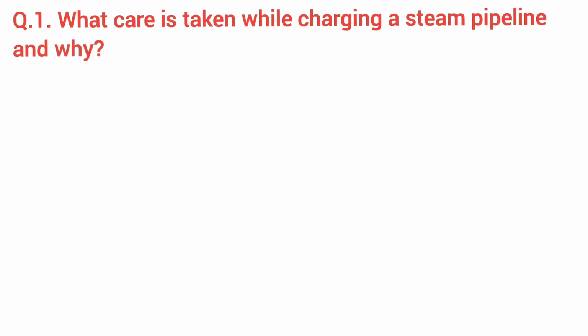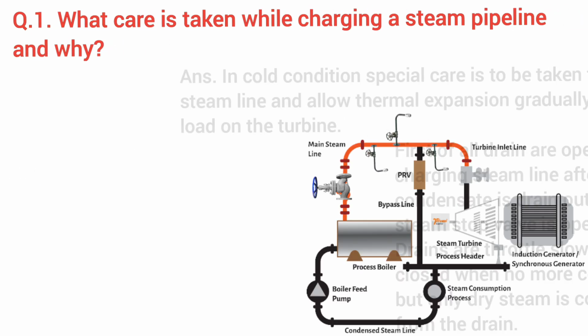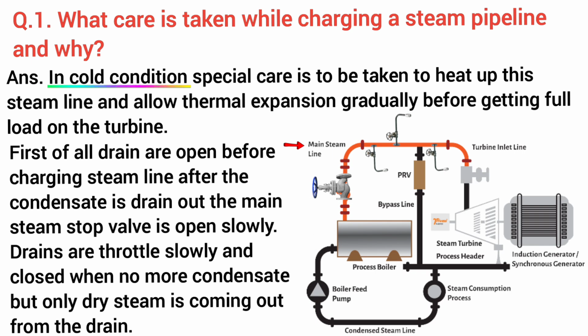What care is taken while charging a steam pipeline and why? In cold conditions, special care is to be taken to heat up this steam line and allow thermal expansion gradually before getting full load on the turbine.